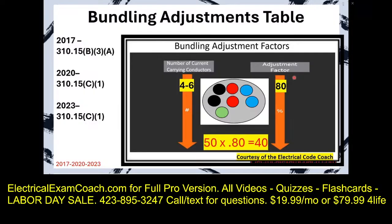What they're saying is because of the amount of wires inside of this pipe or cable, the wire cannot dissipate the heat safely. So you have to reduce how many amps the wire can handle. So the new allowable ampacity of this wire is only 40 amps.